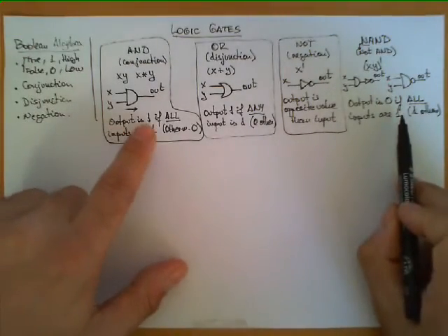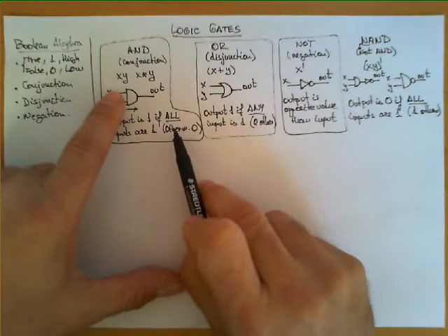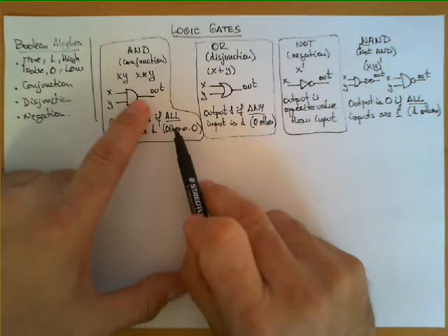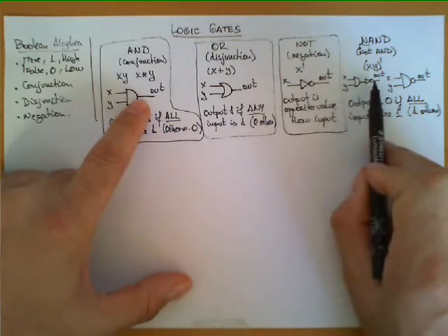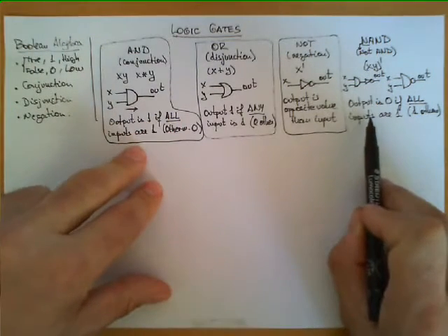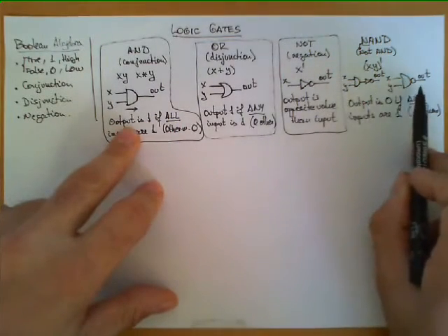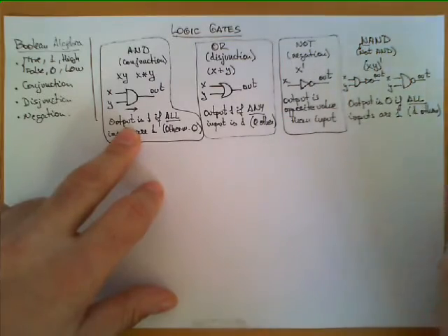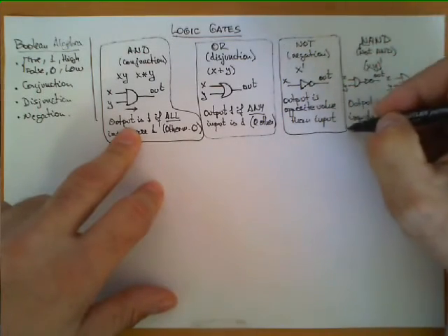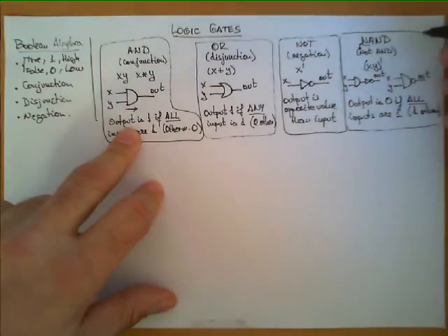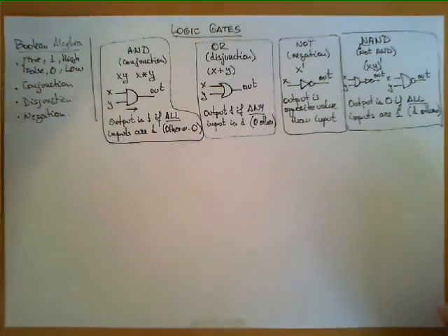Why do we deduce this rule? Because this AND output is telling us that when all the inputs are 1, the output produces a 1. But in here, this inverter switches that to a 0, so the new rule is that the output will be 0 when all the inputs are equal to 1. So this over here describes the behavior of the NAND gate. Let's take a look at three additional gates here.